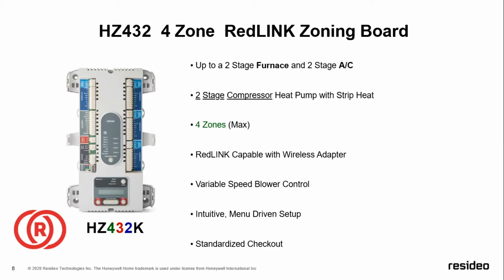Now, for those of you all that like to go the extra mile as far as making your systems fancier than the average 95% of your customers, if you did decide to stage the strip heat, you can actually have 2 stages of strip heat in addition to your 2 stages of compressor heat. So just a small footnote for the capabilities of this particular board.